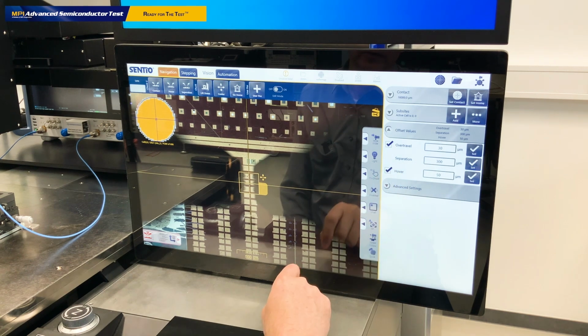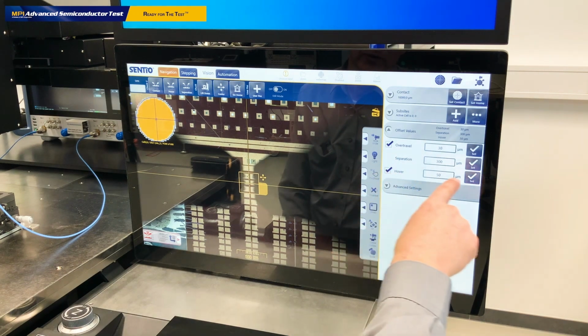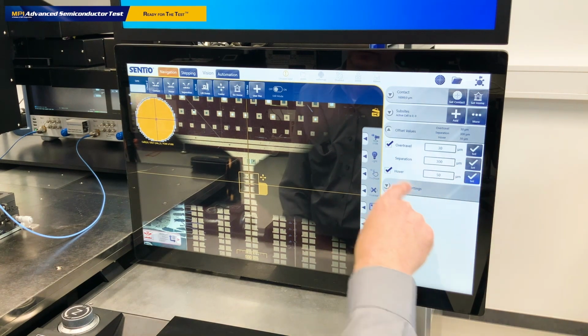Hover actually means it enables a third button which is giving us a navigation level between contact and separation. And that allows us to easily align the wafer to the probe tips. But it prevents larger movements. So as soon as the wafer is going into the stepping function, the chuck would automatically separate. Hover is only used for the alignment of the wafer.